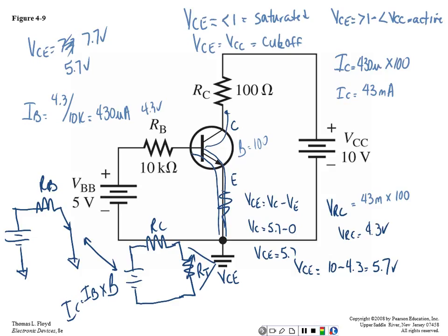So I'll hook this up and I'll see if we got these size resistors. I'm pretty sure we do. And we'll use a 3904 for our calculations. So what we'll learn is a typical beta. 3904 typical beta is around 100. So we can hook this up pretty good. But what's going to happen is I'm going to get a heat gun or a soldering iron and put it across this, and you'll notice that the voltage drop across the collector to emitter goes down because beta changes with temperature. So if temperature goes up, the beta goes up, which means IC would go up.